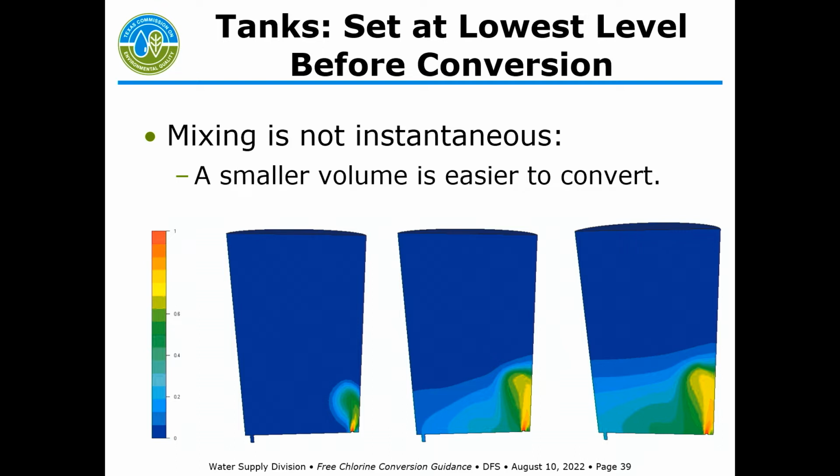Pretend that each of these is a tank. Going from left to right is going forward in time. So basically here in the left tank, you see chlorine coming in the lower right side of the tank, and water is exiting the left side of the tank. A few hours later, you go back and look, and you notice the free chlorine has spread more through the tank,